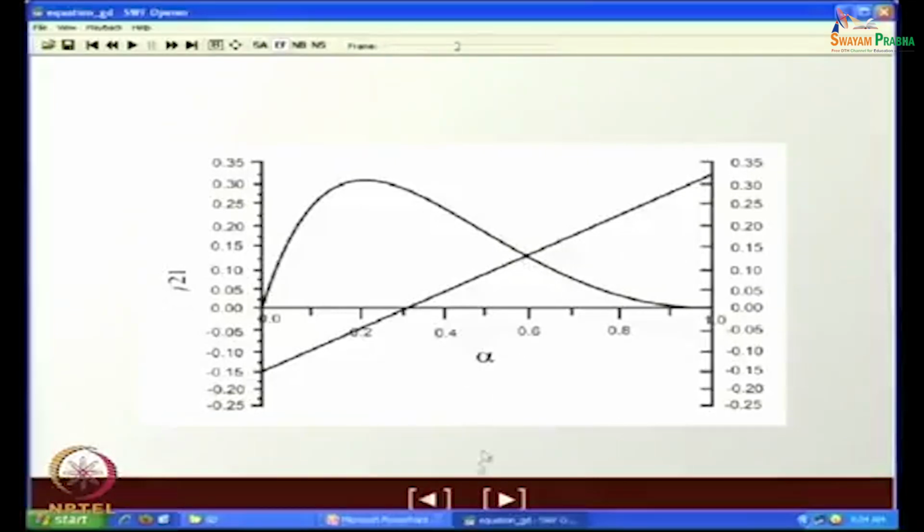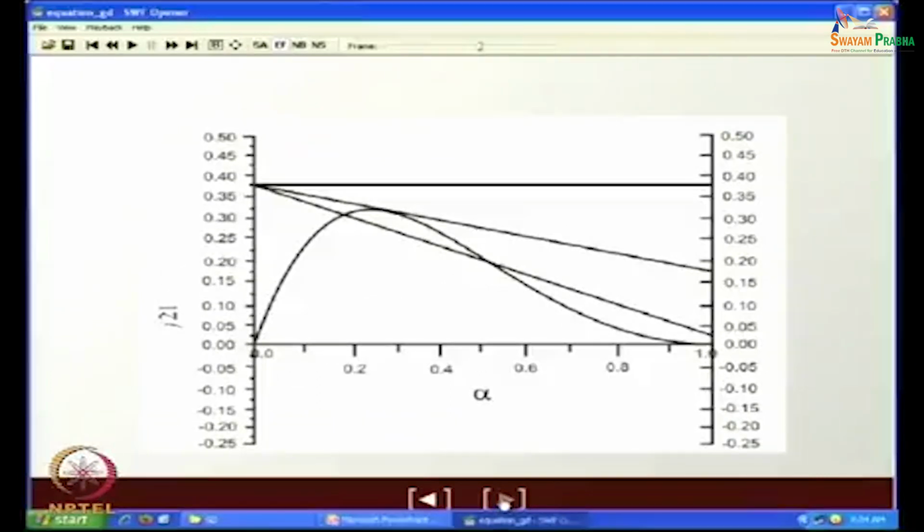Clear? Achha. Then next we found out that for counter current operation, gas up, liquid down, either two solutions are possible. Under one particular situation, only one solution is possible. Beyond that, no solution is possible. In other words, counter current operation with gas up, liquid down can occur only under a set of conditions.